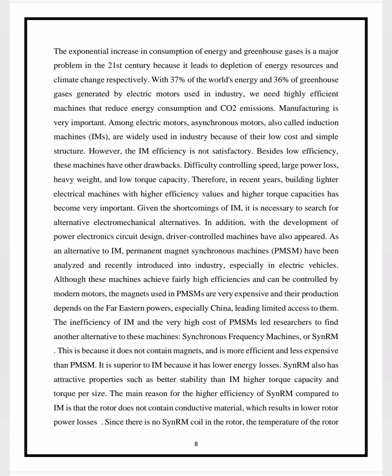The main reason for the high efficiency of synchronous reluctance motors compared to induction motors is the rotor, which doesn't contain conductive material. The rotor is the important part of these motors, which results in lower rotor power losses. Power losses will be minimized.